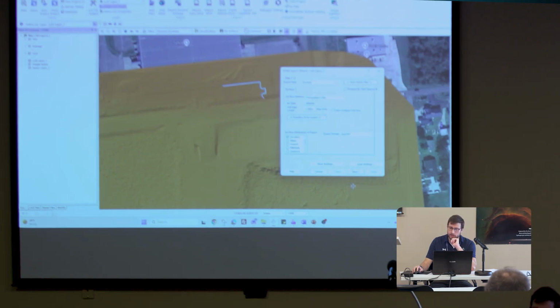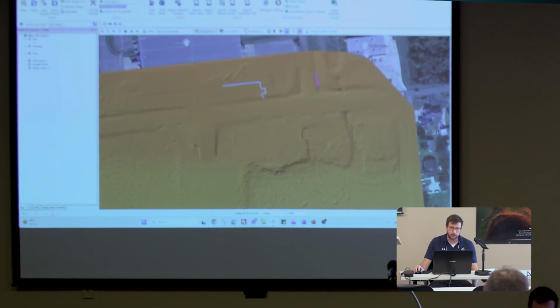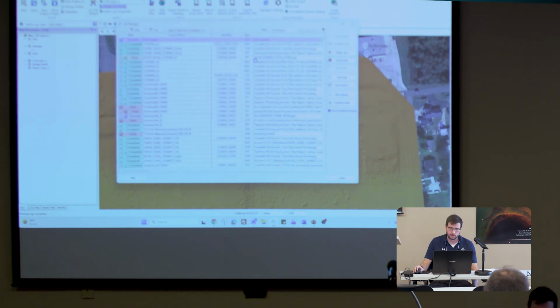We'll do a 1 meter cell edge length to save us time. And in step 2, use draw window and map. Click on the draw tool button. I'm going to left click and hold. I'm just going to draw it over our little wall feature here. Hit next. And then I'll just run this one more time. And it should go much, much faster.